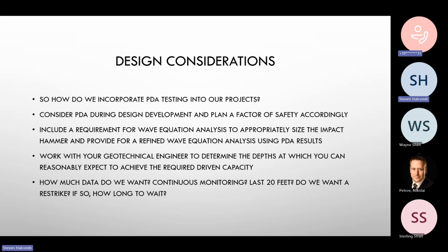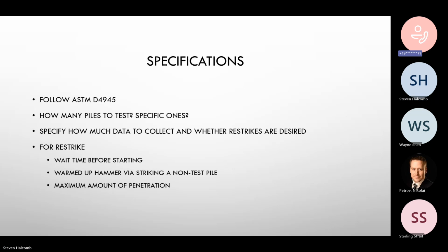A lot of times the silts are ones where it's good to do a restrike a couple of days later, give them a little bit of time to set up. Sands and gravels, especially gravels, not as beneficial. Clays, good to do restrikes, but it can take a really, really long time, and that's usually not as realistic. So usually the silty sands and the sandy silts get the most setup in the least amount of wait time, for the most part, relative to their setup.